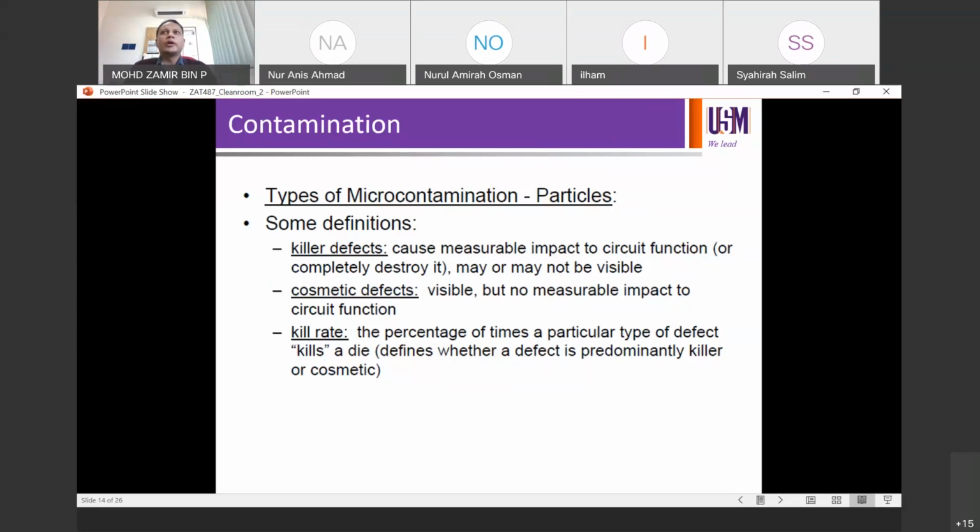You have to open the equipment, go through the process, troubleshoot, and run test wafers. In the fab we have test wafers. Test wafers are wafers we don't use for production, like dummy wafers. You can run dummy wafers through equipment and process recipes to check whether they are okay or not. So you need to do the test run.